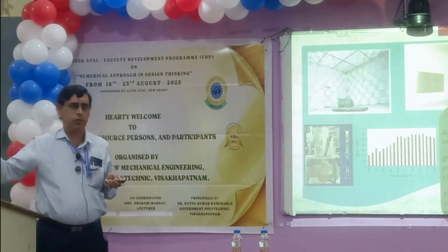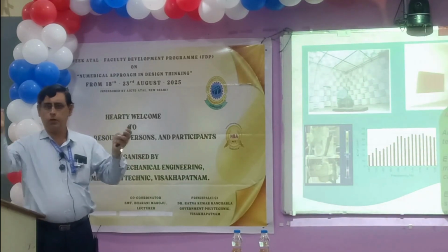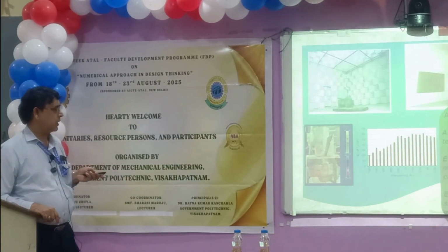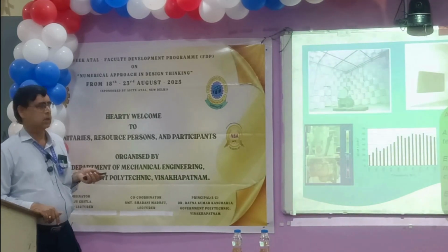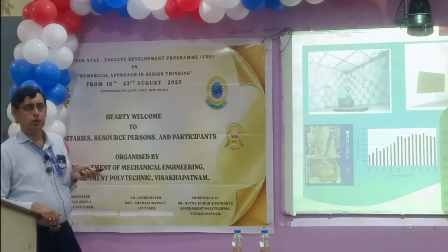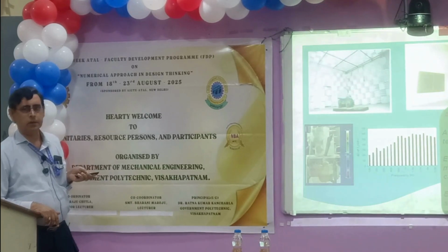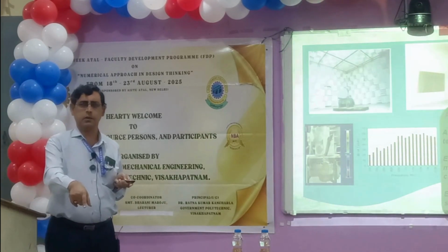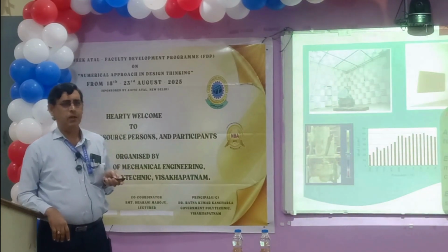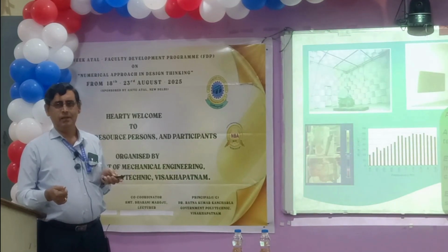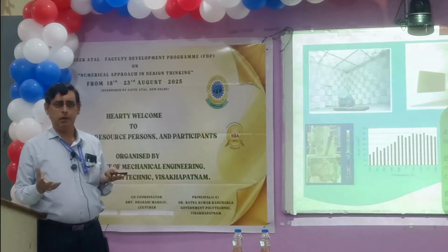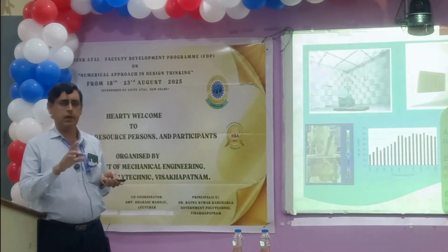So there are six total walls as per this room. Four walls here, ceiling and the bottom floor. So all the 6 if you are treating, then it's called fully anechoic. Otherwise, it is semi-anechoic. So in this case, why it is created is to know exactly how much sound this particular equipment is producing. Otherwise, what happens if you are testing the same equipment here? What will happen is the reflection also will add to the sound that you are measuring. Whereas if it is completely absorbing, only the sound produced by your equipment will be measured. That is the absolute measurement.